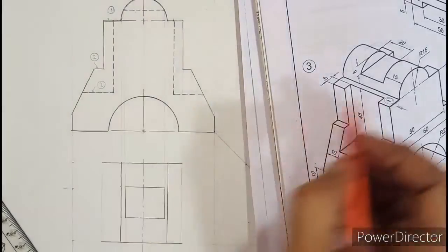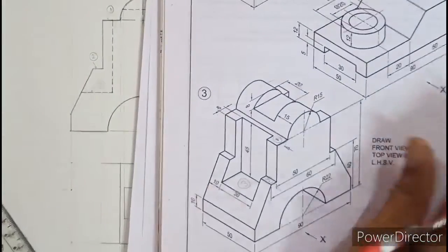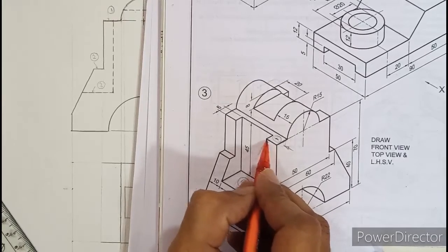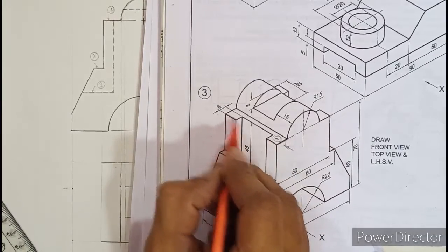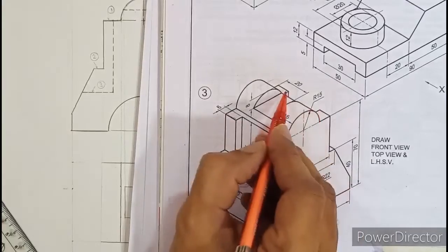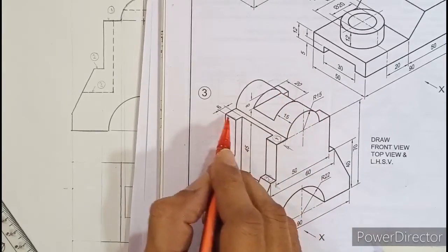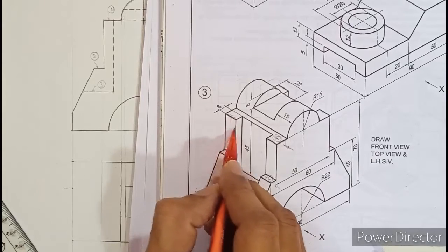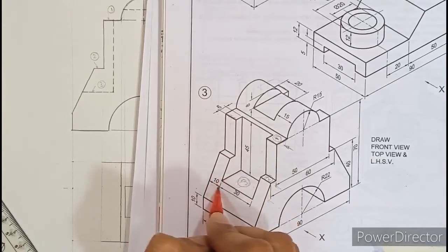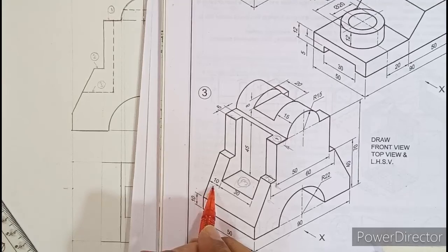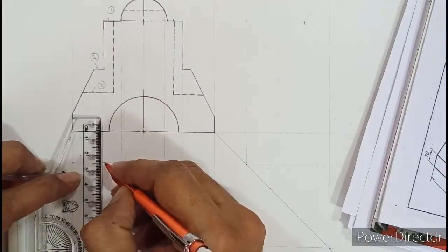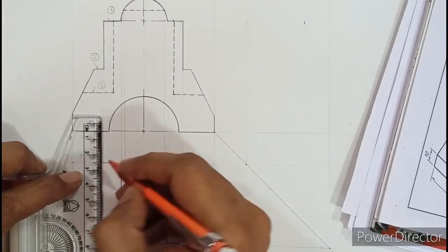Once all the 4 edges are darkened, we go back to the question. See this edge, then you need to move inside to get an inner C. So you need to understand where this edge is. The dimension is not given straight away where you want. You need to search somewhere. If you search down, this edge is 10 mm. It is given here, the same as this 10. So you need to move down by 10 from all the 4 sides.